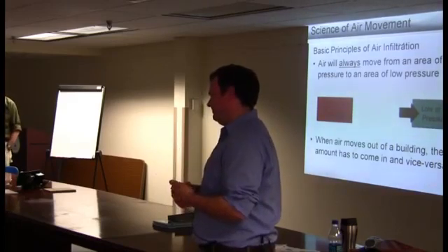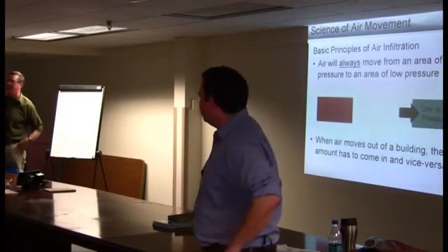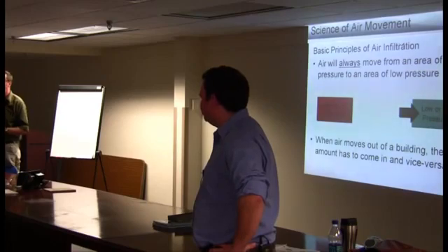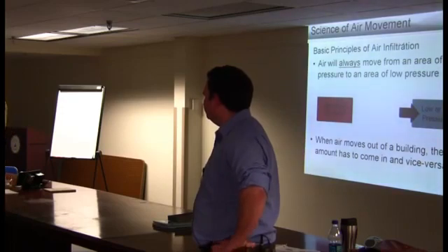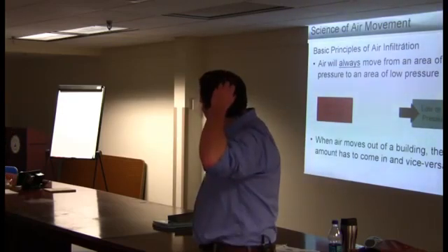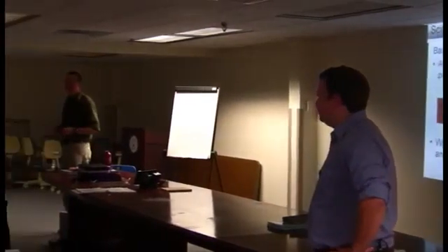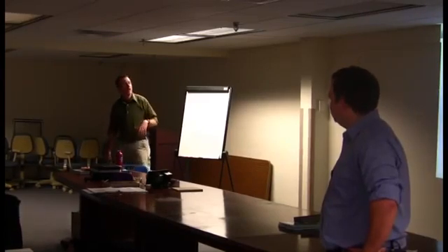One thing too, you kind of notice that term infiltration, it sort of implies air leaking in. That's kind of a cold climate mindset. It's people in a cold climate that don't want infiltration because that means cold air is leaking in. But appreciate that in our climate, it's conditioned air leaking out. It's the same thing. So infiltration, it's really better to call it air leakage. And the same amount that leaks in is equal to what leaks out. And I think that's always worth remembering.